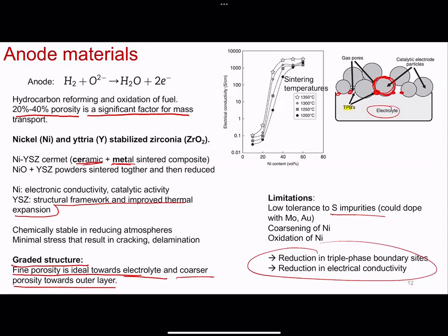And the other issue is that there are higher temperature phases that have higher ionic connectivity. If you want to bring them down to lower temperatures, you have to substitute to stabilize them, like yttria-stabilized zirconia. So that is one strategy, but now we go back to my original argument: you start doping in, you start making your phase diagrams more complex, and you start stabilizing decomposition phases.